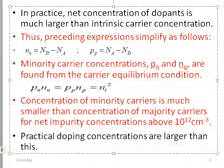And in this case, whenever you multiply the minorities in the N-type times the majority, which are the electrons in the same N-type, that is equal to Pp times Np, that is majority in the P-type multiplied by what? The minority in the same P-type. That will give you ni squared, and that is the mass action law we introduced in our lecture number 1.